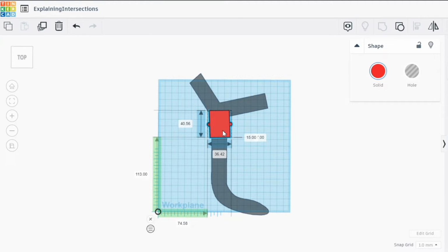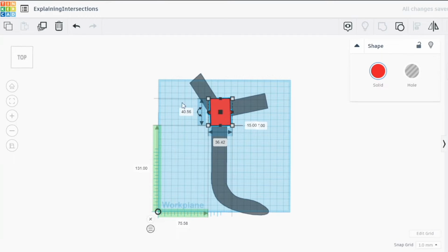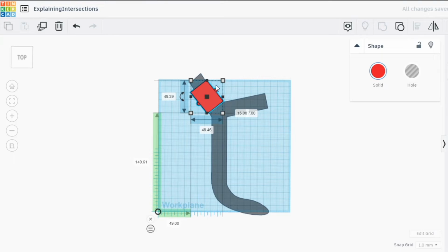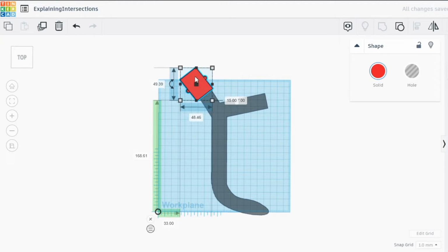And if we continue, the object reaches the junction or the intersection in which both the sensors detect black light. Since its major application is in sectors where it will have a predefined path, our code is fed in such a way that at this junction, it has to move right or left according to the destination it has to reach. Let's assume it is moving left, then it will use the logic of this curved path here to take a left turn. Then it will use the code for a single normal line following to move further. So this was the steering mechanism, and I would request Vivek Mirani to explain the circuit.